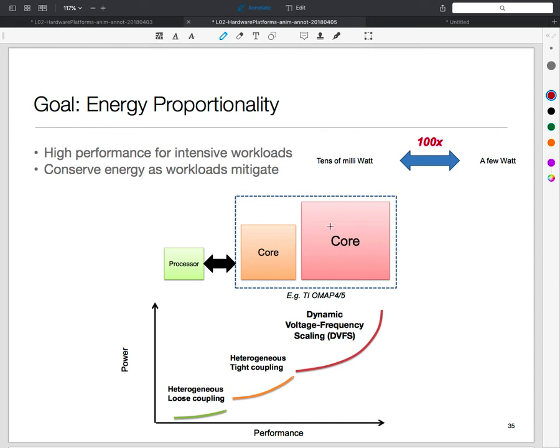Our little watch has two processors in it, right? It has the Bluetooth processor and it has the main processor. Part of the reason the Bluetooth processor is there is that it is perhaps doing something very dedicated. But my guess also is that you want to put the whole thing to sleep and then be woken up when a packet arrives over the Bluetooth link. So that little processor can be up and running.